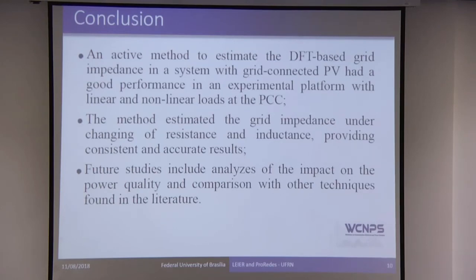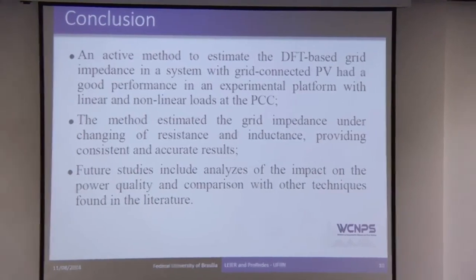So, an active method was proposed in this work for estimating the impedance in a grid-connected PV system based on the DFT. It had a good performance in an experimental platform in the presence of linear and nonlinear loads.